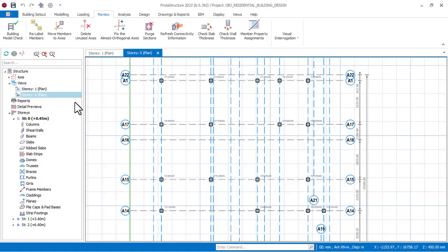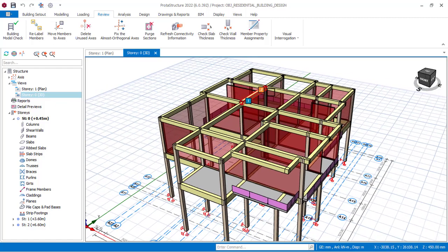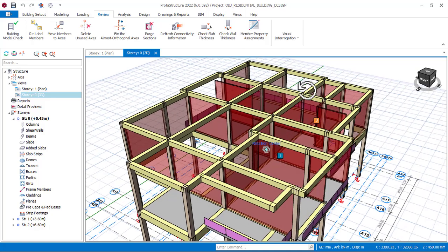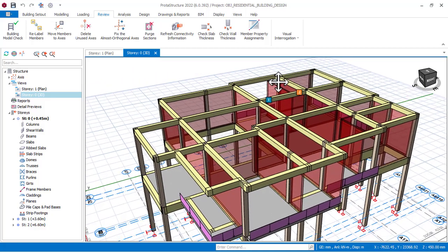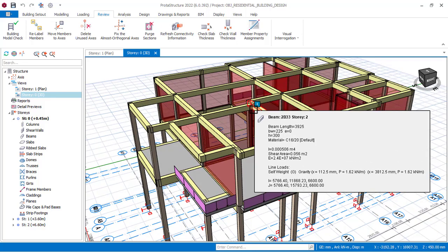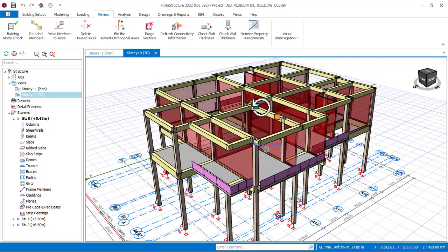That is one. Two, the bearing capacity of the soil is 150 kilonewton per meter square. Okay, so right now you can see that this is the best choice of foundation to choose. Also, from the soil report, there is no settlement issue, and the place also has no water logging.